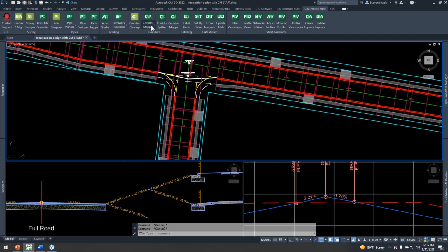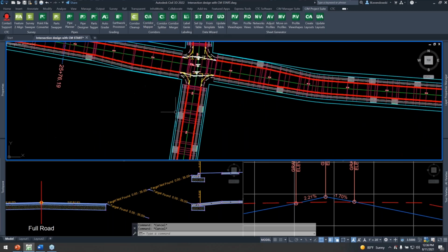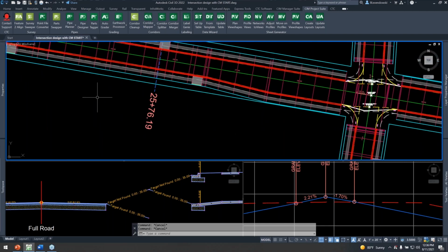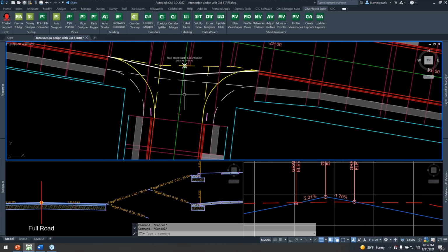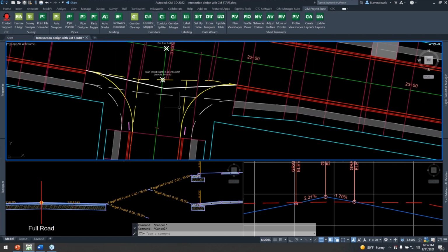That being said, there's a couple other supporting tools I'll mention here. You can automatically generate layers from subassemblies, so they're named the same as the subassemblies, or you can rename whole sets of subassemblies based on layers, or layers based on subassemblies. They're pretty simple utilities, but they support this whole workflow. All right, sorry about the confusion around the targeting there. Let's move on to these intersections a bit more, okay?